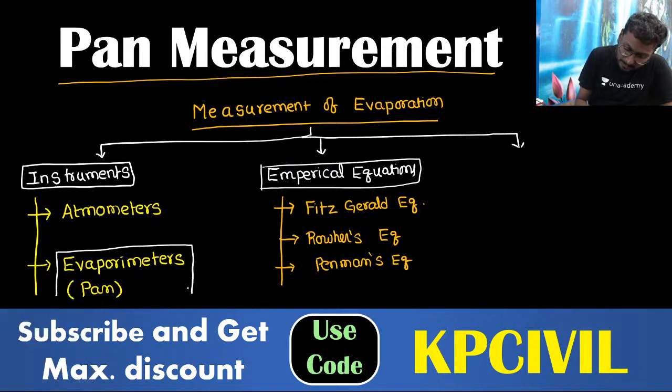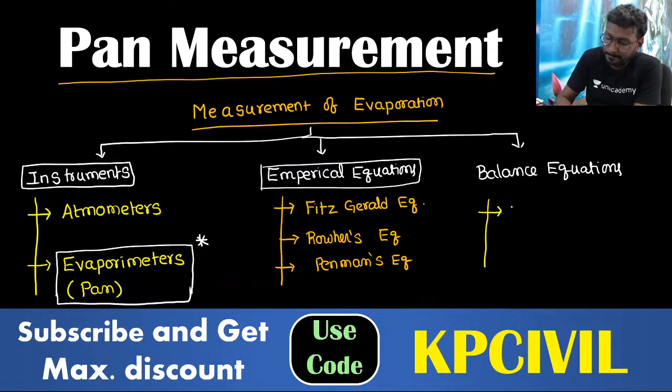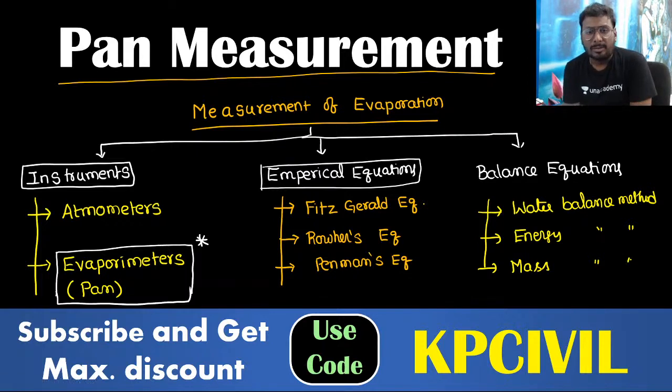The most important method of measurement of evaporation is the evaporimeter or evaporation pan. Other than this, we are having balance equations. What are the balance equations we are having? Balance equations include water balance method, energy balance method, and also mass transfer or mass balance method. So these are the different methods of measurement of evaporation.